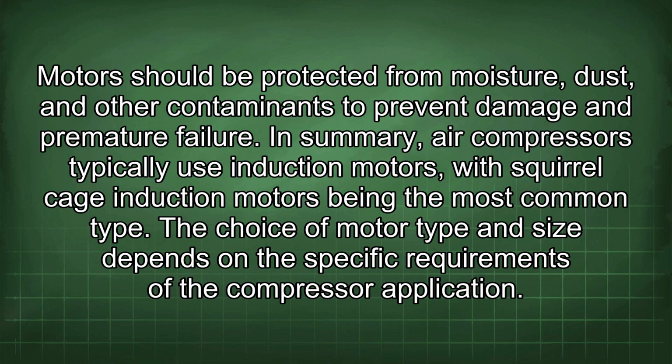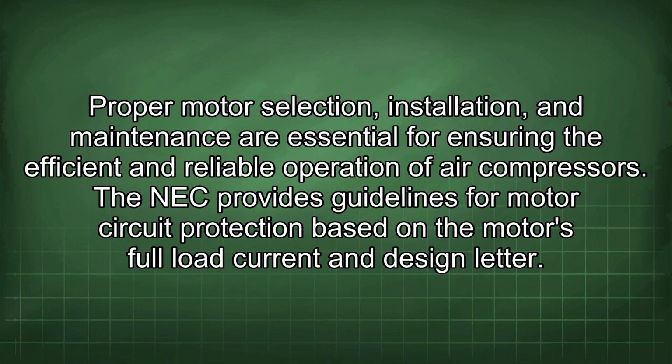In summary, air compressors typically use induction motors, with squirrel cage induction motors being the most common type. The choice of motor type and size depends on the specific requirements of the compressor application. Proper motor selection, installation, and maintenance are essential for ensuring the efficient and reliable operation of air compressors. The NEC provides guidelines for motor circuit protection based on the motor's full load current and design letter.